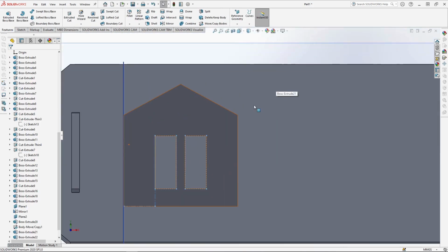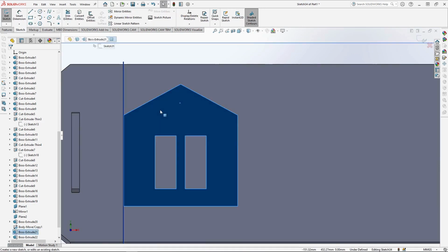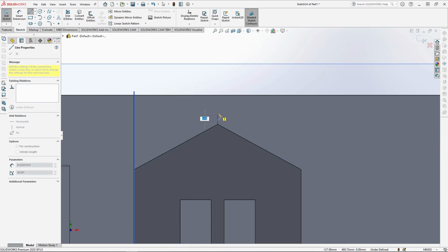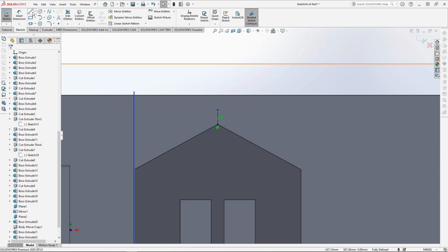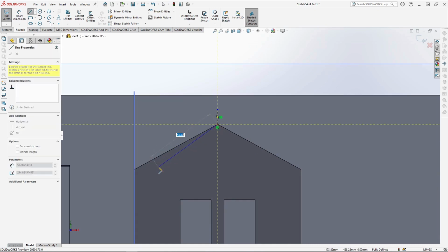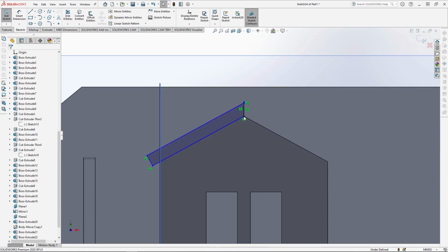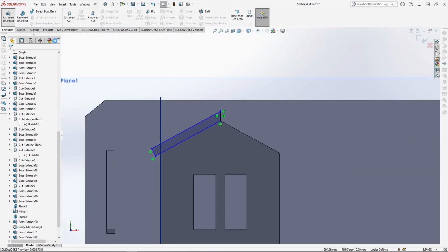To add a roof to the window box, start a new sketch onto the front of the window. Just like the canopy roof, draw a guideline up from the top point and make sure that it's more than 11mm. Then with the line, go along the front edge here by 80mm, then at a right angle up by 9mm, and staying parallel to the line, go up to the guide and close it up. Extrude the roof panel by 9mm in direction 1.